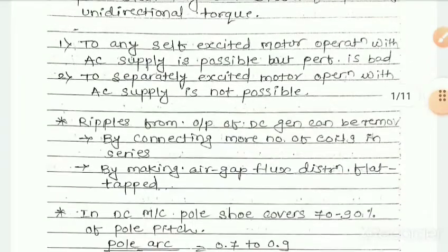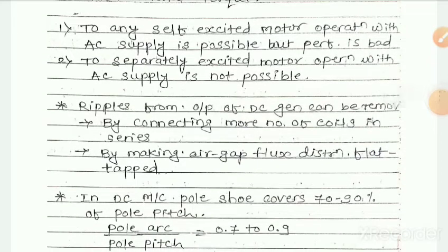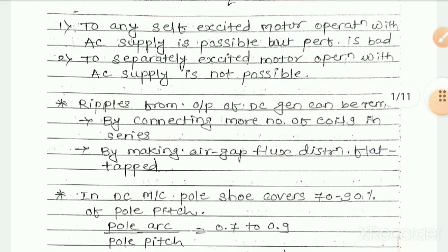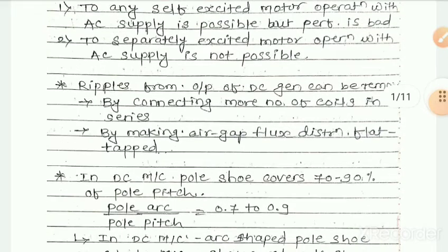Now, for any self-excited motor, operation with an AC supply is possible, but the performance is bad. For a separately excited motor, operation with an AC supply is not possible.